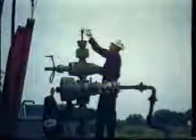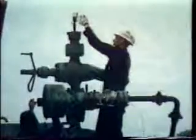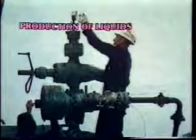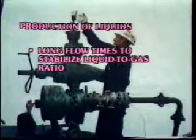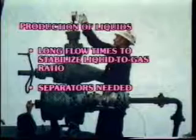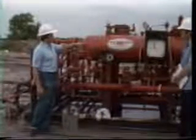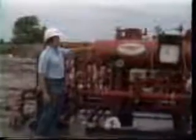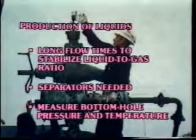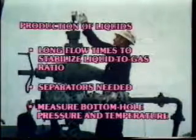Many gas wells do produce liquids, be it condensate or water, which cause fluctuations in the rate and pressure measurements. In some cases, long flow times may be needed before the liquid-to-gas ratio stabilizes and test data become valid. Separators are needed at the surface in order to measure gas and liquid production rates. This separates all the gas away from the liquids, whether it be oil and water or just oil or water, one or the other. In addition, because correlations of surface to sand face pressures are inaccurate for two-phase flow conditions, bottom hole pressure and temperature measurements are recommended.